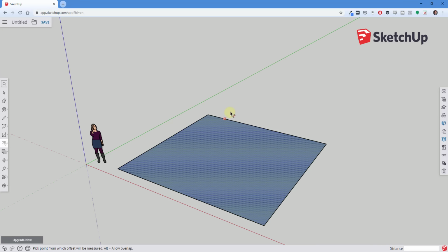And what we want to do is you're going to notice when you mouse over this, it turns kind of a highlighted color in here. What that means is this is indicating that the offset tool will offset based on this square. And so we're just going to move our mouse inside of here, and we're going to single click, and remember not to hold your mouse button down, simply single click in here.